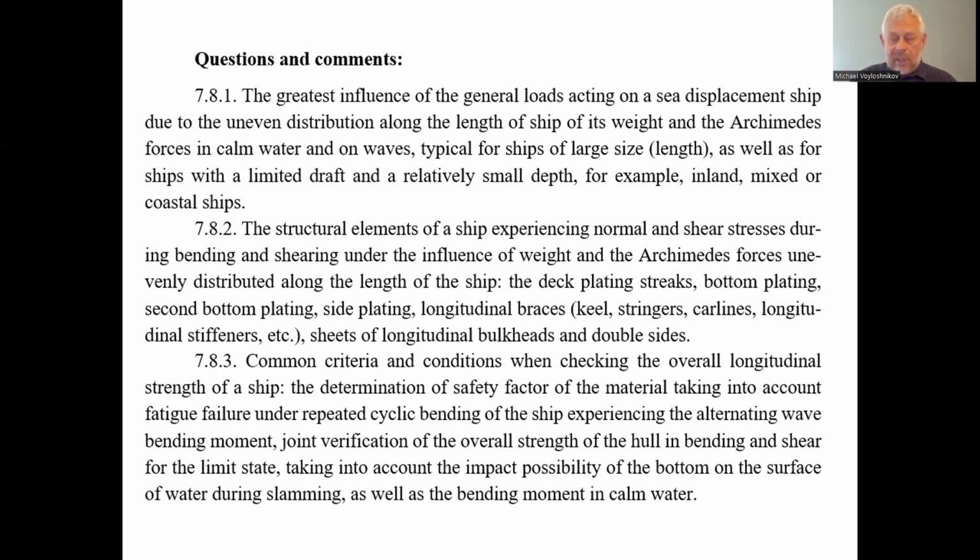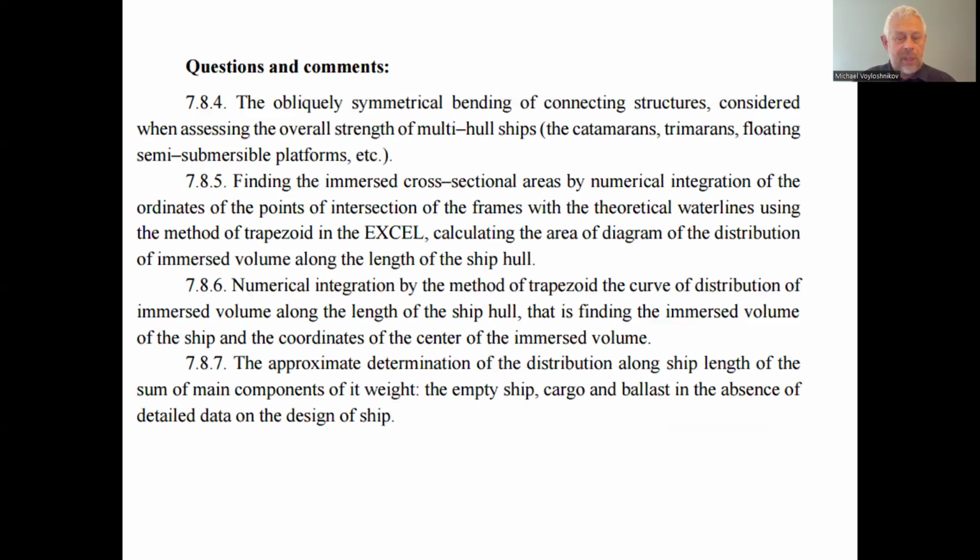And this is definitely the case where we adopt the assumption that, due to practical navigation, it is likely to use ballast in the other peak to balance the trim if the ship is partially loaded. This is more important, more characteristic for ship operation, than to allow the trim and to allow slamming and to increase the safety margin, etc. This is not so characteristic for the operation and the calculation of the ship. So we have to adopt only one, with the exclusion of duplicity in the criterion of the ship strength.